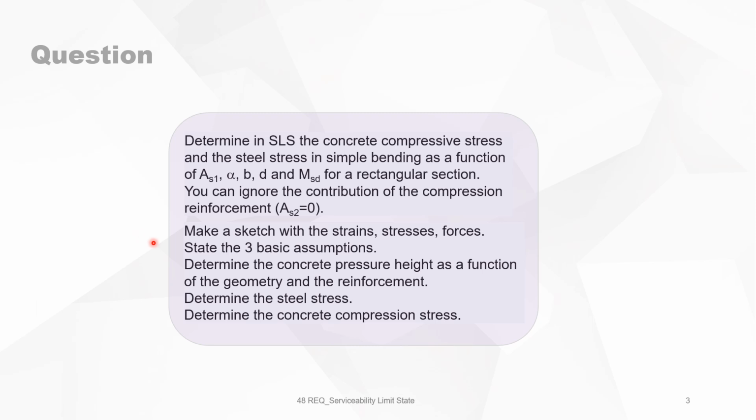Make a sketch with strains, stresses, and forces. State the 3 basic assumptions. Determine the concrete pressure height as a function of the geometry and the reinforcement. Determine the steel stress and the concrete compression stress.